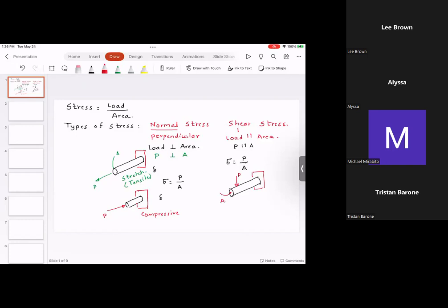Now, what happens when you have the shear loading? What I want you to do is look at this element over here. This is the expanded view of this element. Under the load, you would observe that this element will get deformed something like this. Initially, the angle was 90 degrees. This will get deformed and the angle between the edges will no longer be 90 degrees.